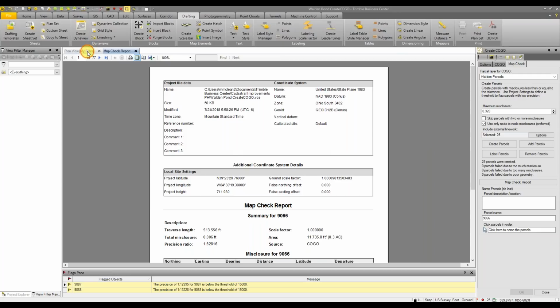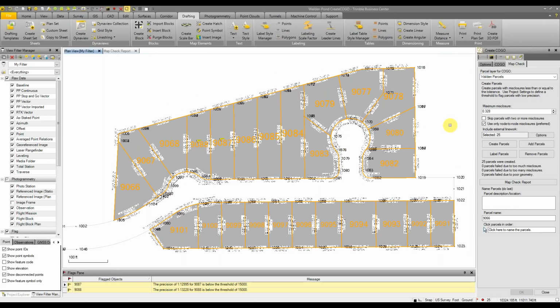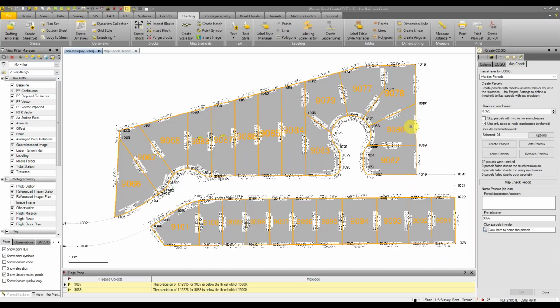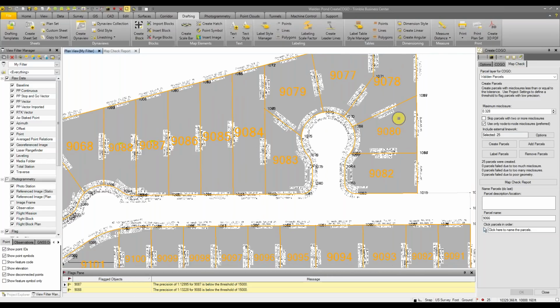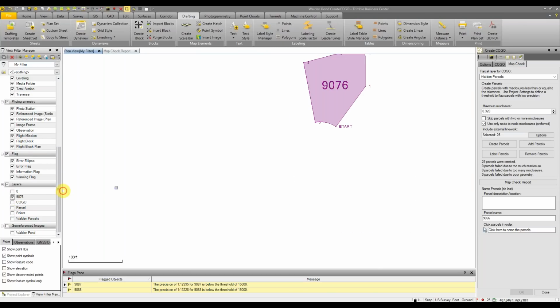Neil was asking, do we have the auto flip so it's right readable? That's correct. In addition to that, you have the ability to right click on a label and do flip side if you want to flip the side on which the label is, or you can also flip the bearing and azimuth.